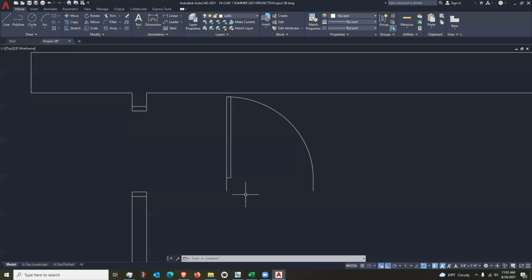So in general, yes, you will put a 5-inch, sometimes a 6-inch door jamb in an exterior wall, just like we showed it. Again, this isn't a materials and methods class, and I don't want to get into the nuts and bolts of the construction process. Believe me, you will go through that. But for this class, yes, 5 inches is the correct depth for that door jamb. Okay, great, thanks.